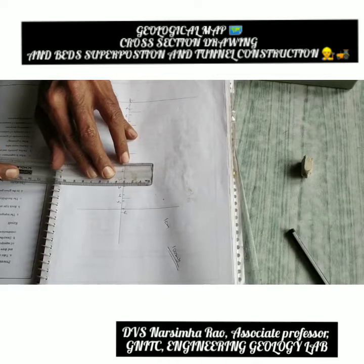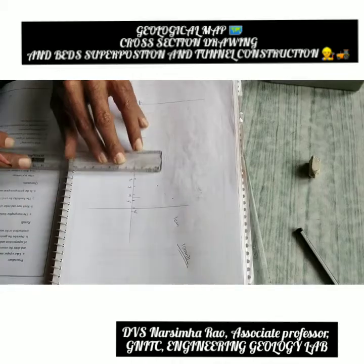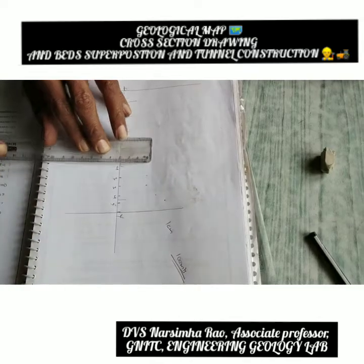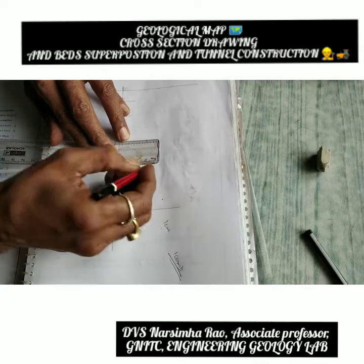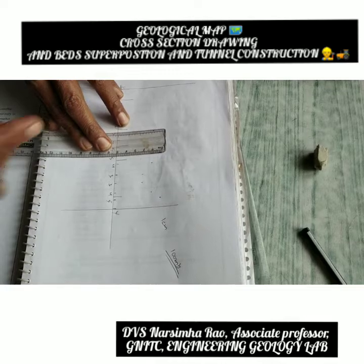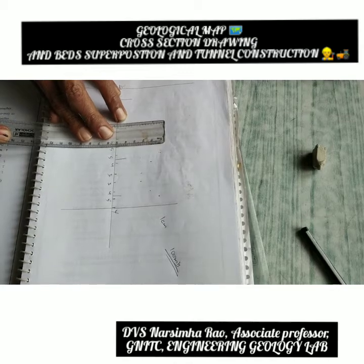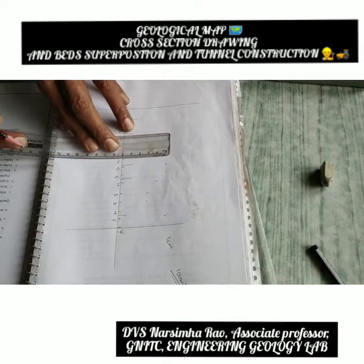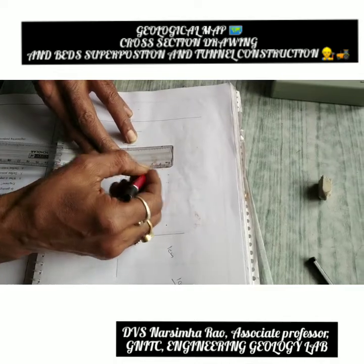Again you are taking 300, so keep the 3 centimeters here, keep one dot here. Again you are drawing 300, keep the dot like this. Same thing, again you are going for 400. Now you are going for 400, one dot here, then again 500. So this is fine. Now what you are drawing? You are drawing the geological cross section. So you are seeing the hill in the side view. When you are seeing the hill in the side view, how it looks, you are drawing. This is the geological cross section of the area.